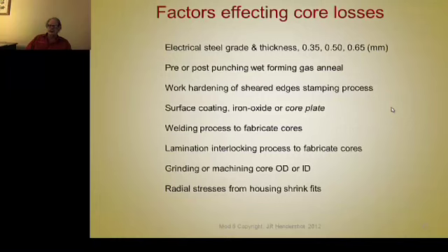It's better to have several small welds on the OD, and they should be of the order of 1.5 millimeters wide and 1/4 millimeter deep. That should be the penetration to hold your cores together. And if you have 4 or 6 or 8 welds, depending how big it is, in the center of a tooth, and they're TIG or laser welded, you shouldn't have any core loss problems. But there again, you could test one that's been bonded versus one that's been welded.